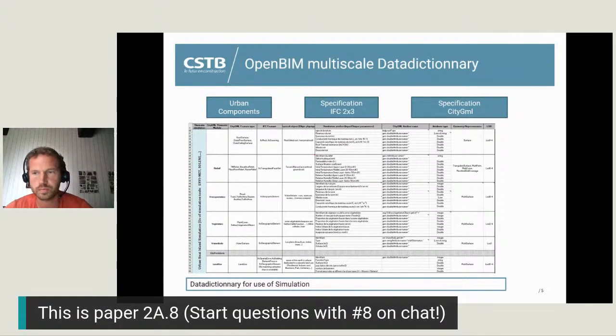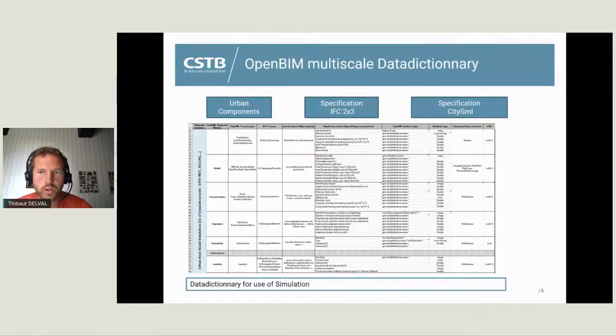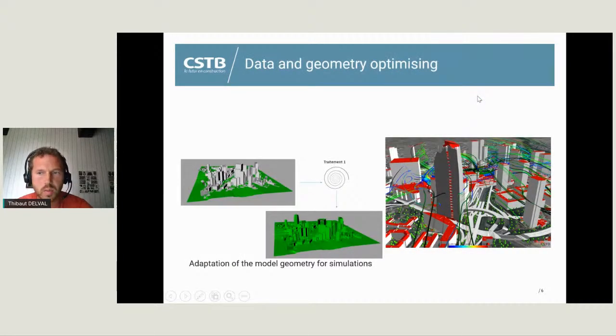To assess comfort, we had to perform many simulations like aeraulics, acoustics, and solar reflection. For each simulation, we had to structure the required data into parameter sets using BIM standards. So we use CityGML for the city environments and the IFC standard for the building model.